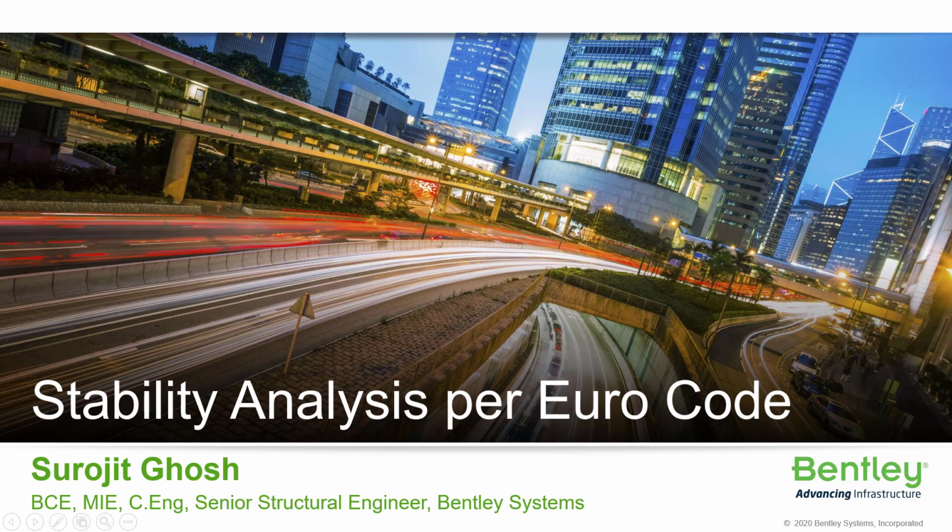As Bishwa mentioned, in AISC code, performing the direct analysis method ensures the stability of the structure, considering all the conditions like imperfection, material nonlinearity, stiffness reduction, and so on. Now in EC3 code, there is no such method available as direct analysis. Rather, there are several sections mentioned in this code which handle the stability analysis and design criteria. So, if you want to perform stability analysis, you need to consider and incorporate all these guidelines.